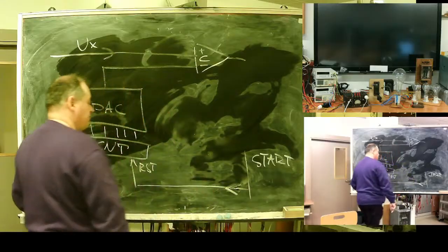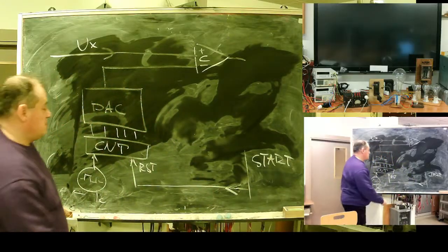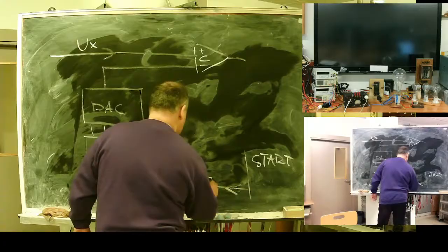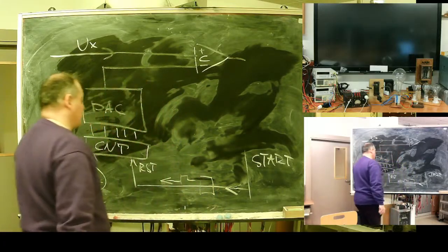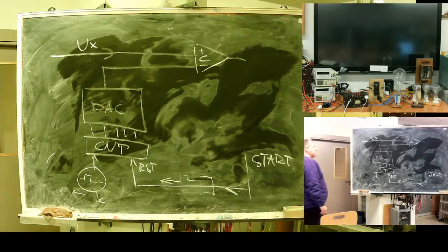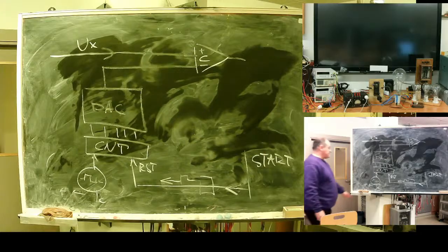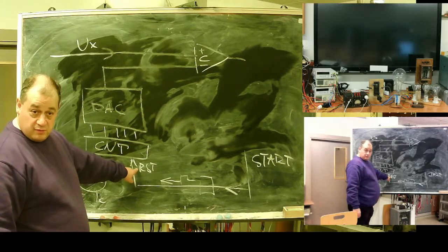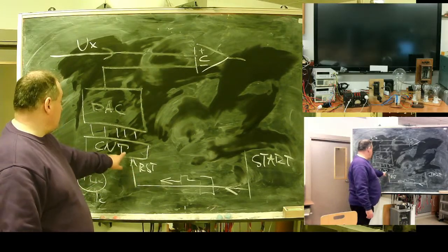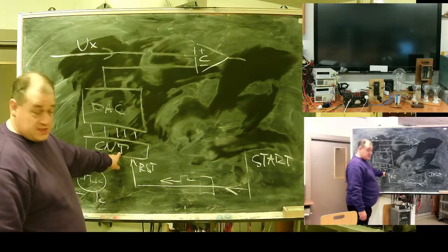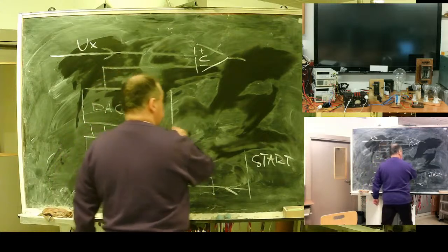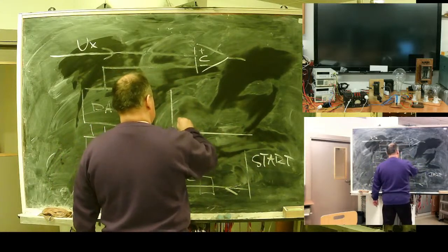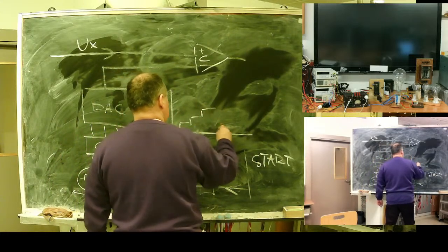Here it is better to have pulse forming. I need to send a pulse. What will happen if I send a start command? Reset will be formed and the counter will start counting from 0.